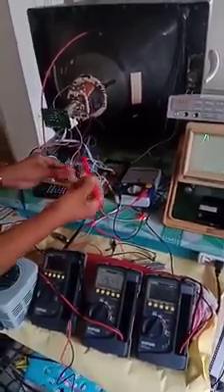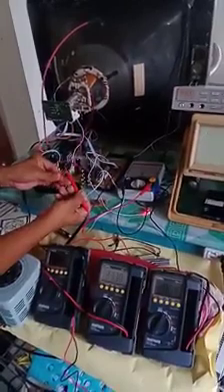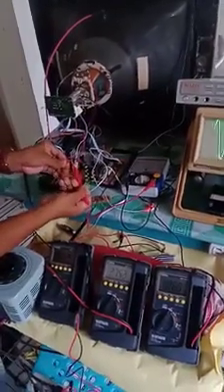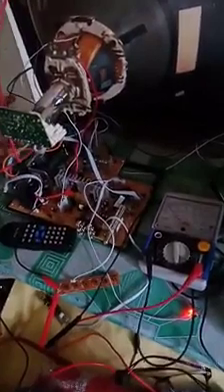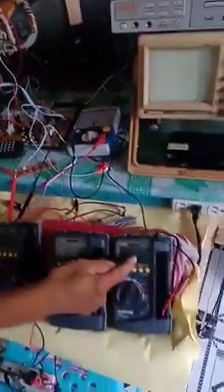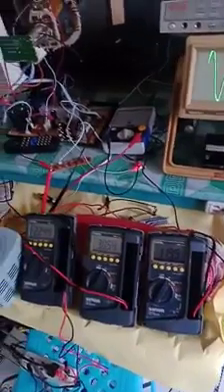Okay, like for example this one, we will permanently connect. The positive side of the voltmeter is actually connected to the output of the regulator, because this horizontal output transistor, the collector, is actually supplied with DC voltage from the low voltage power supply. And actually this voltage 120 volts is supplied by the switch mode power supply.